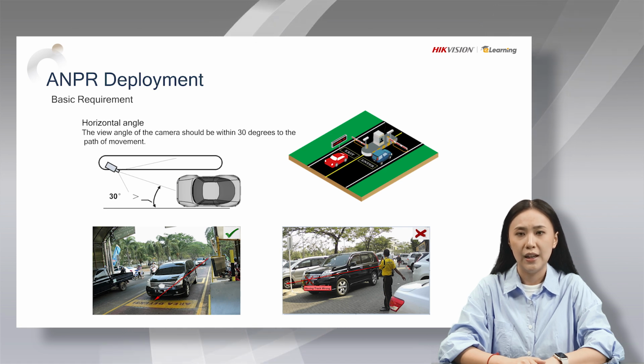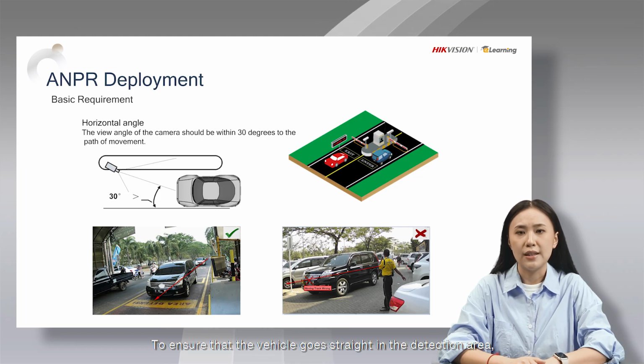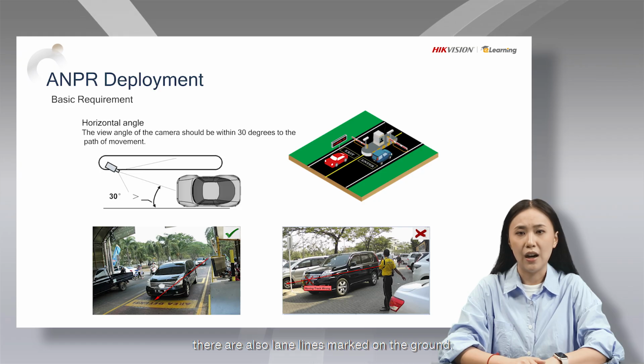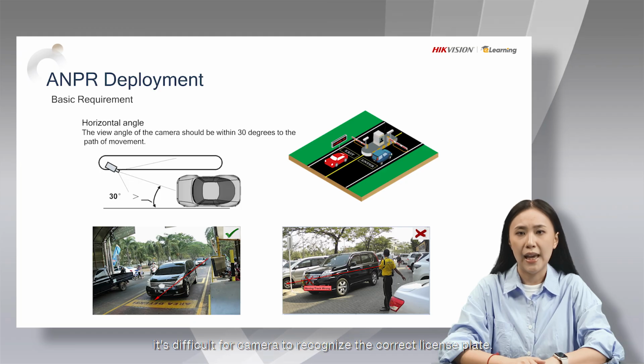of movement. The sample on the left side clearly shows the appropriate horizontal angle to the camera. To ensure that the vehicle goes straight in the detection area, there are also lane lines marked on the ground. And through the photo on the right side, we can see that if the horizontal angle is above 30 degrees, it's difficult for the camera to recognize the correct license plate.